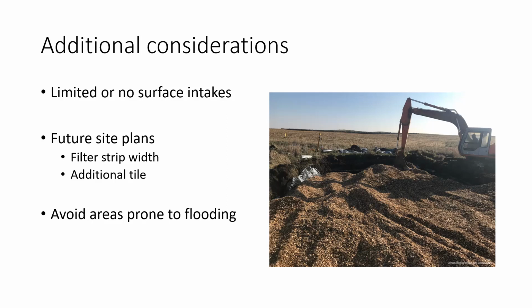Also, is there going to be new tile going in, or is this main going to be the same size moving forward? Is there any thought at all about maybe, if it's an 8-inch main, bumping that up to a 10- or 12-inch main in the future? You could always get the control box larger and make it work for future conditions. But if it's a smaller control structure and then that main gets upgraded, that would become a choke point. You don't want that to happen. So just have that conversation to make sure we know what that tile is going to look like for the next 10 years.